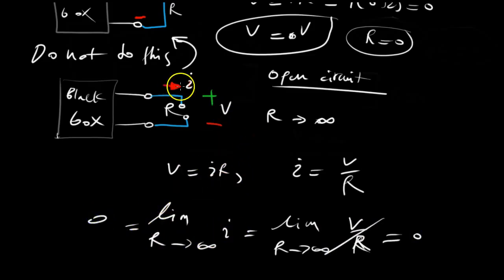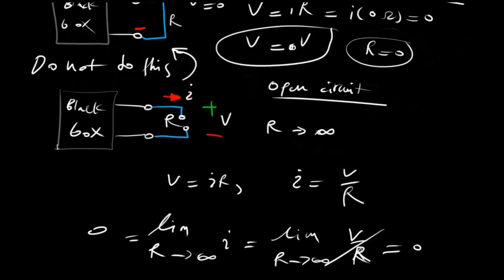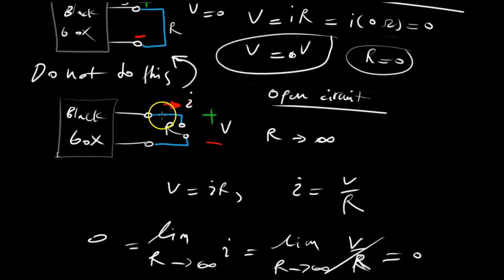So no current is going to flow. That makes sense because current takes the path of least resistance, which in this case has nowhere to go, and the resistance here is so huge that in engineering we just say infinity. So no current is going to flow, and you're going to see the full voltage, whatever the voltage was before, across here. So that is the open circuit voltage.